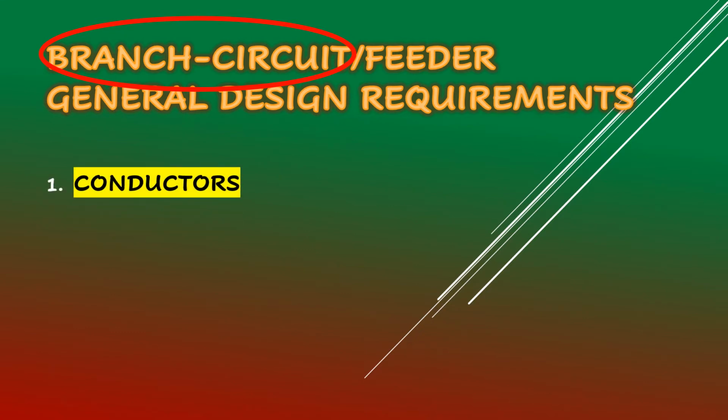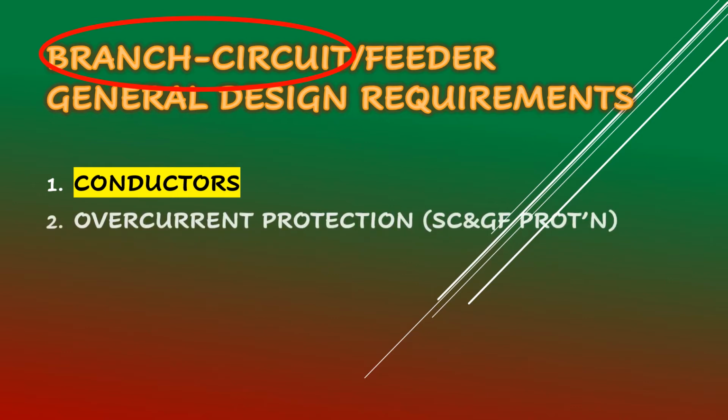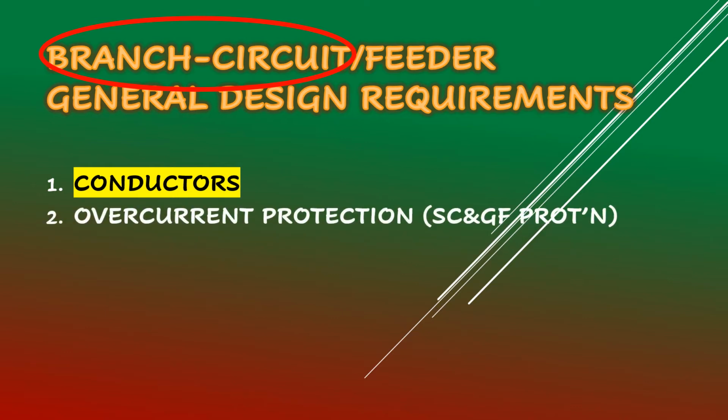Number one, conductors. Conductors are very important since they connect the power supply and the load, so we need to design for these conductors. Number two, overcurrent protection, or for the motor it is called short circuit and ground fault protection.